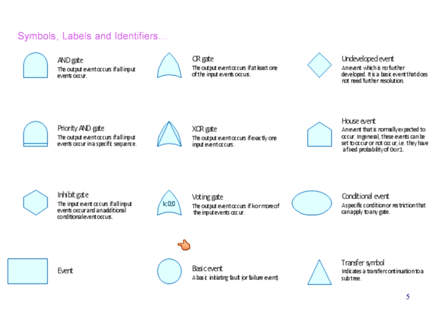Okay, and you have one more symbol called a basic event. The shape of the basic event is a circle. A basic event is a fault or the final event, and a rectangle is simply called an event. So we are going to use the main symbols: one, the AND gate; two, the OR gate; third, the basic event; and fourth, the event.